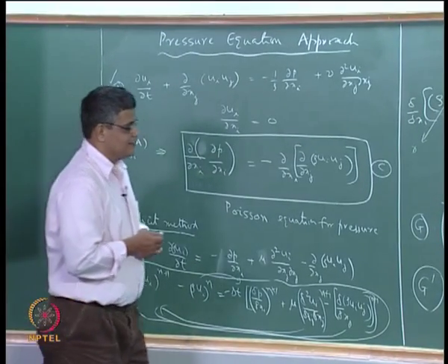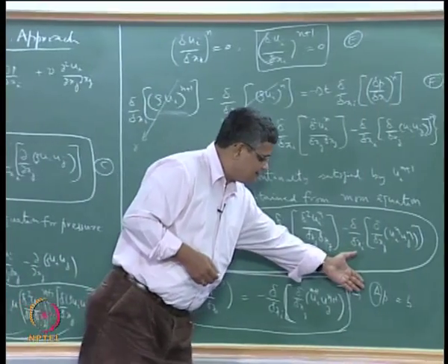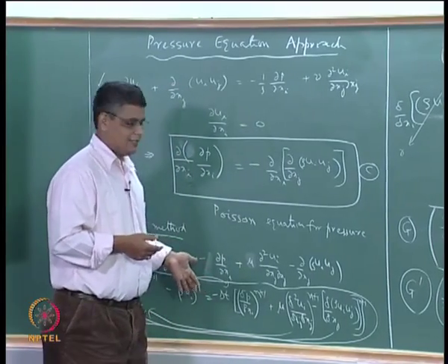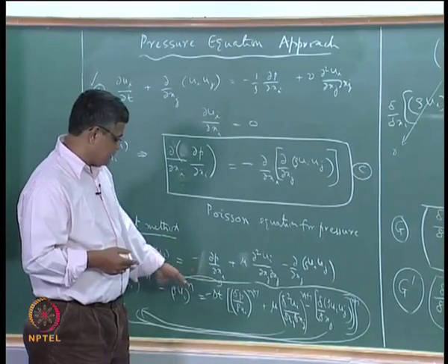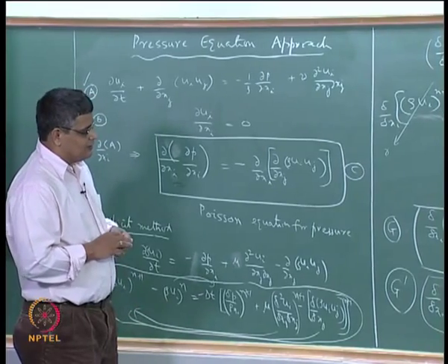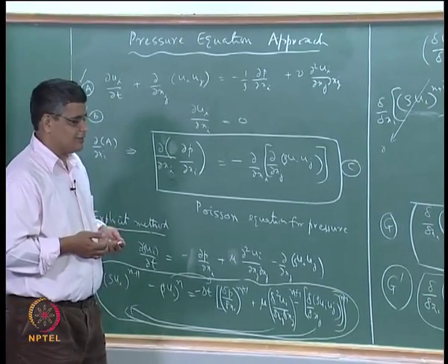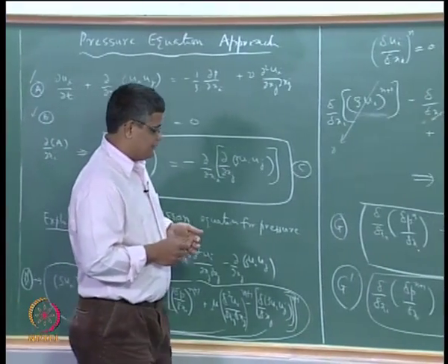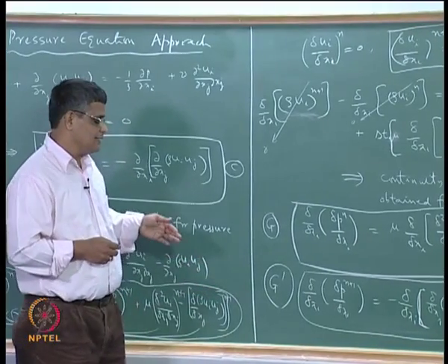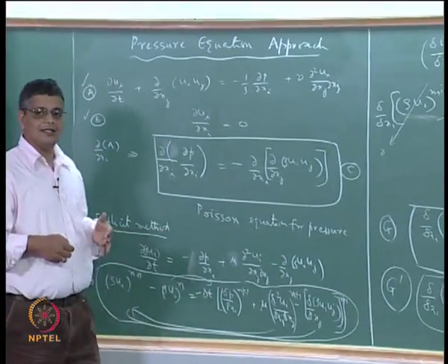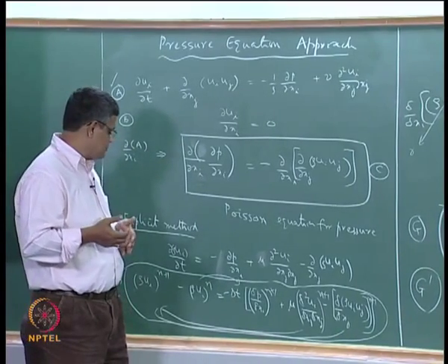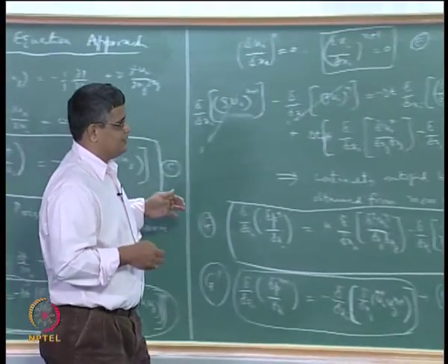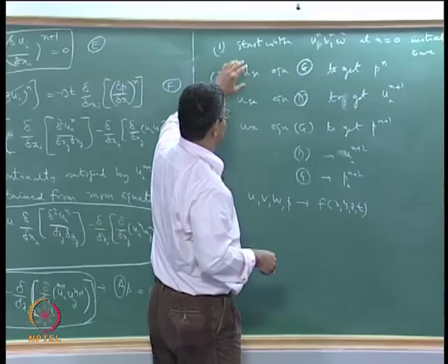But having said that, typically this equation will probably be much more difficult to converge than this equation, which is a convection diffusion type of equation. So one has to really try out and see whether the computational overhead that is required for an implicit method is really worth the additional large time step that is made possible in an implicit method as compared to an explicit method.